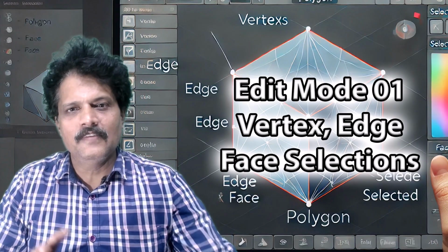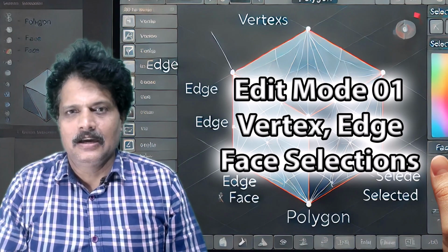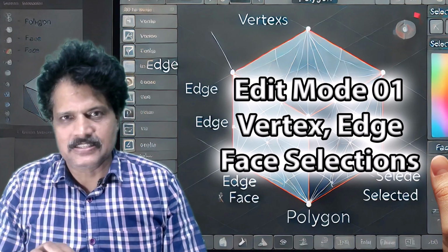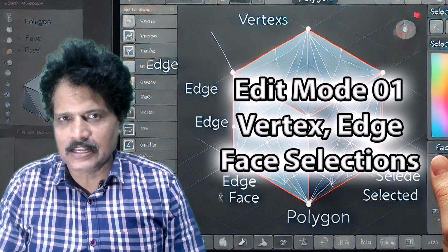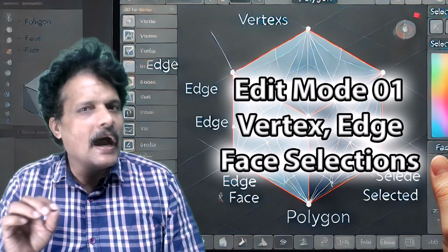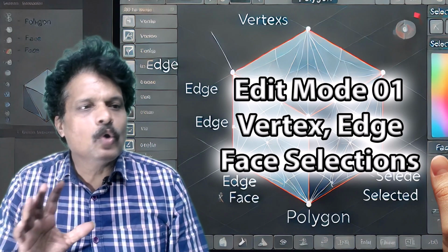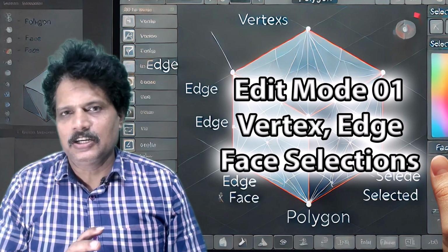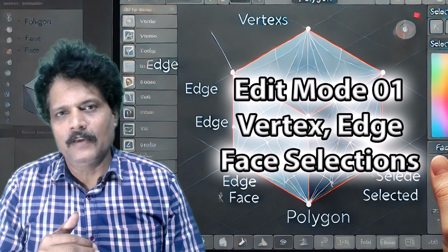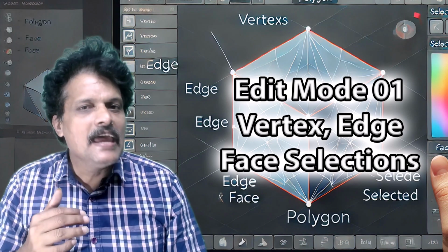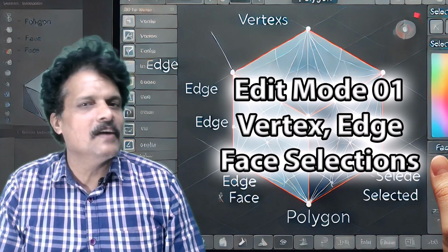In this session we explored what is a vertex, what is an edge, and what is a face. And we also discussed box selection, circle selection, and edge loop and edge ring selection. So in our next session, we are going to continue with this selection, and we are next going to work on another kind of modification, which we call extrude and insert. So this we are going to discuss in our next session.